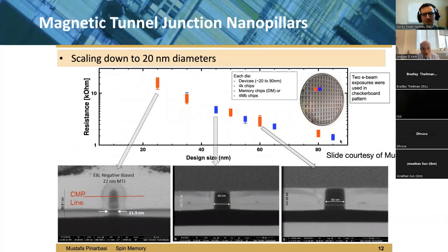As you expect, as you make the junction diameter smaller, the resistance goes up. The resistance is inversely proportional to the area of the junction. So you have flexibility in the size you choose and many other parameters you can take when you make these junctions. And it's very sophisticated technology, actually, particularly carving out these nanometer scale elements. And because the magnetic materials usually don't etch by reactive etching, you have to do a physical process. And so you have to worry about where the material goes. And you don't want it to be deposited on the edge of the MgO, which would shunt the device and actually not make it a tunnel junction.